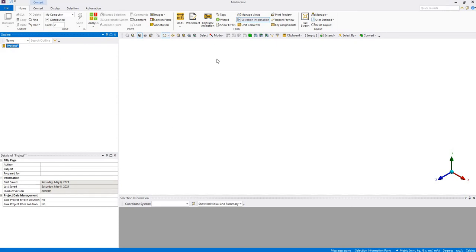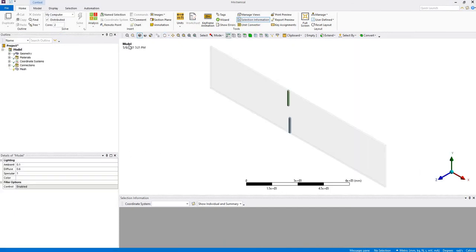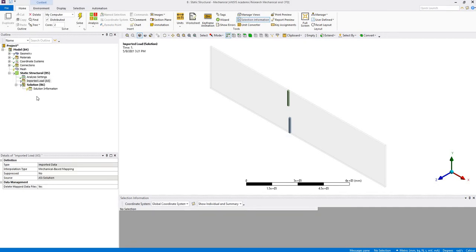All right, it sometimes takes a while to load. Again, a regular CFD solver and FSI are different in computational time. It takes almost about twice the time because you're doing coupling. But one-way FSI is way faster.